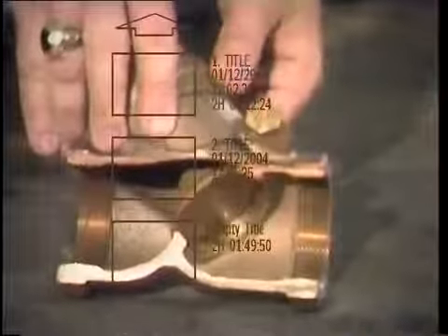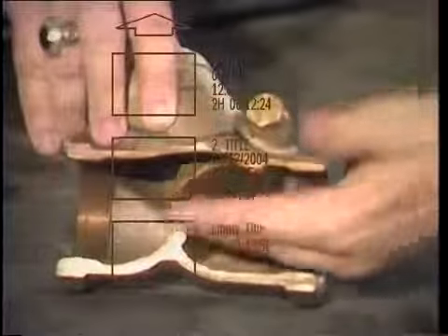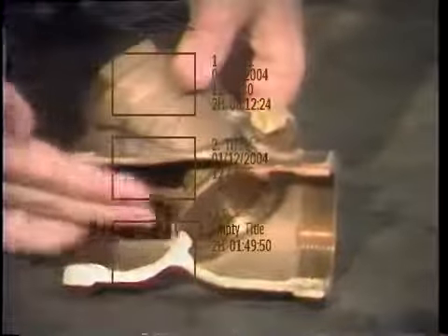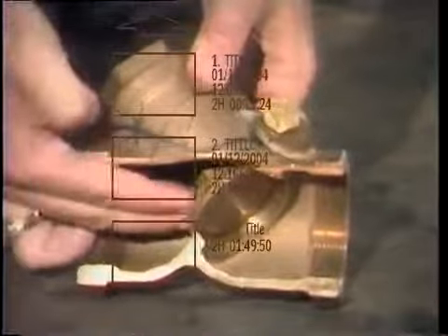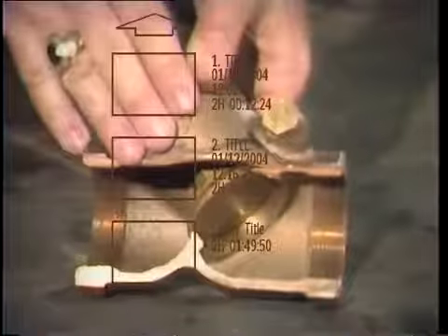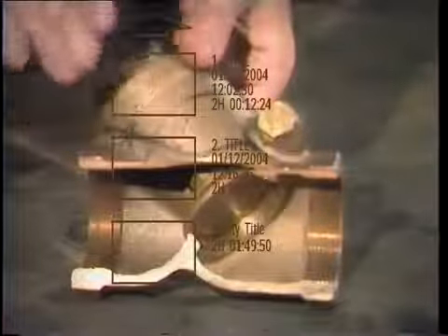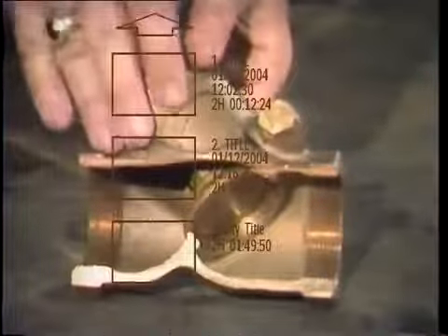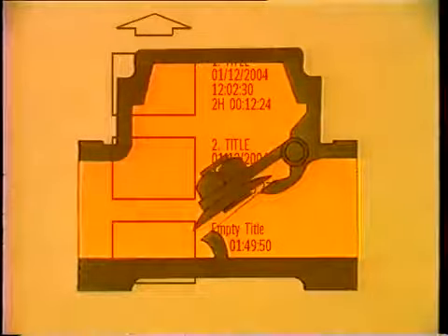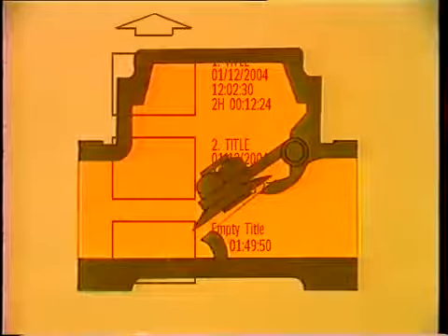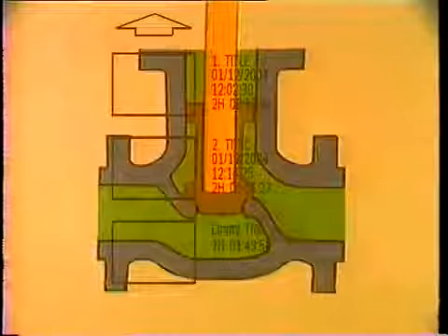There's one more basic valve design I'd like to talk about before we break. It's the check valve. Now, a check valve will permit flow in one direction only. It is designed to prevent any backflow of fluid within the piping. However, most check valves cannot be used as stop valves. Most will only close if the flow stops or if for some reason it tries to reverse its direction. There are three basic types of check valves: the swing, the lift, and the stop check.